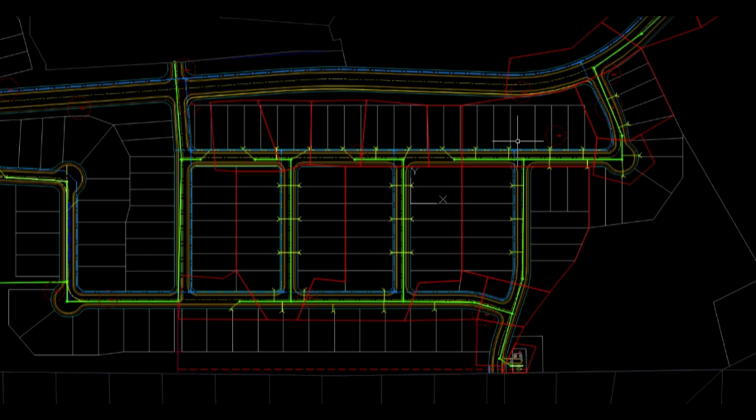When calculating the total amount of flow to a wastewater system so that the pipes can be sized correctly, there are two main inputs: the number of people contributing to the line, and the infiltration area contributing to the system. All other inputs are geometry dependent.